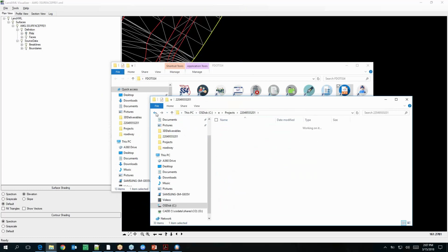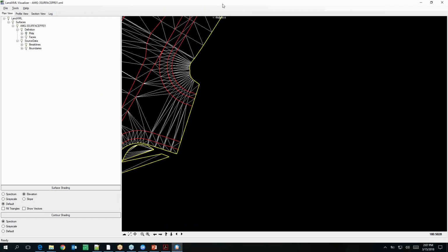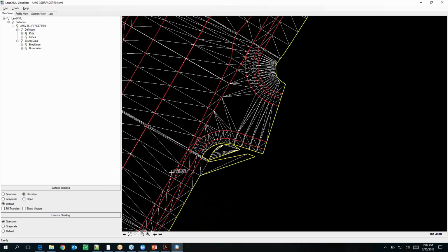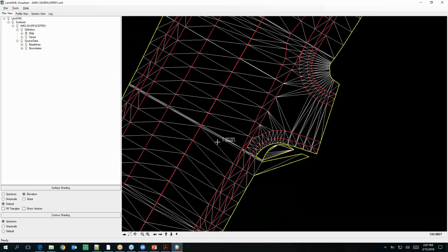And even the 3D lines, what is the size of the 3D lines file? To me, that's even smaller. I'm looking at this and it feels like there's a break here, so I think this might be what's causing the problem. Look at all these triangles right here. There should not be that many triangles. There's some kind of break in the surface.